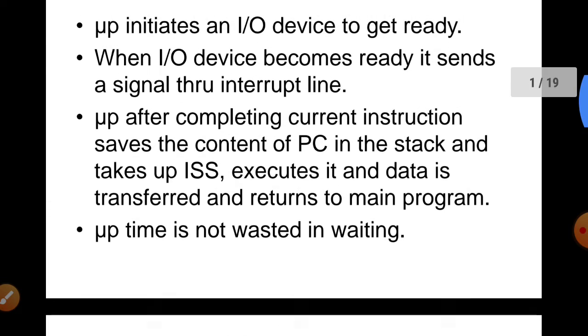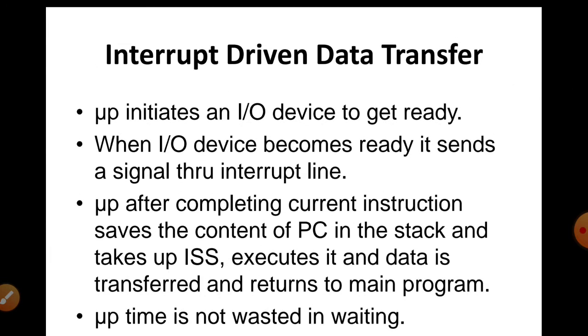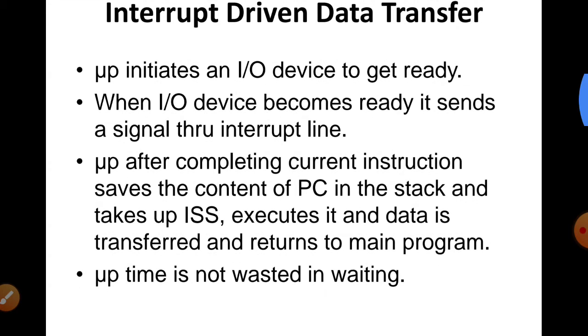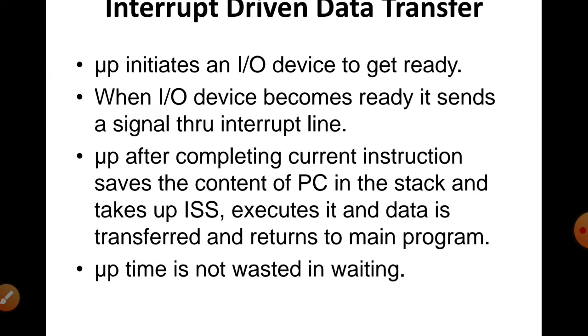Now the interrupt requests are classified into two parts. One is maskable and another is non-maskable. As far as the microprocessor 8085 is concerned, it includes 4 maskable interrupts and 1 non-maskable interrupt. Among the 4 maskable interrupts, one is non-vectored, which requires external hardware to supply the call location to restart the execution.